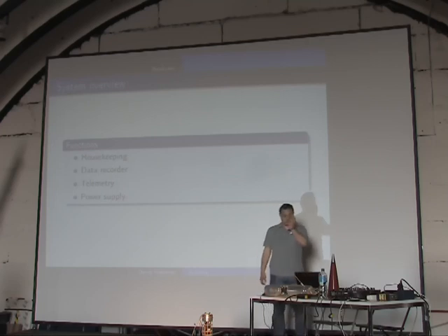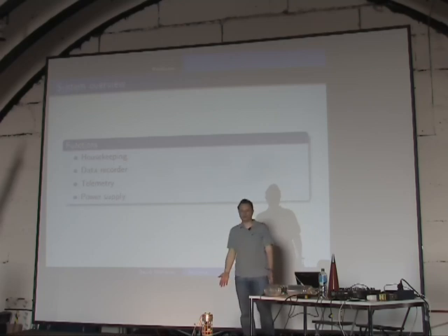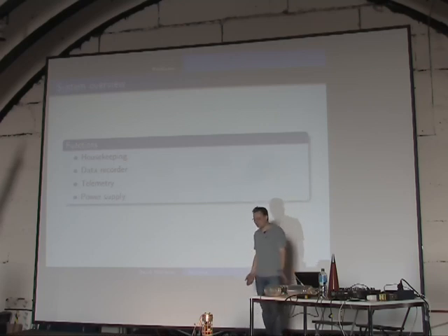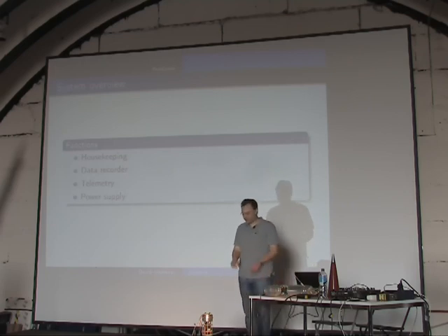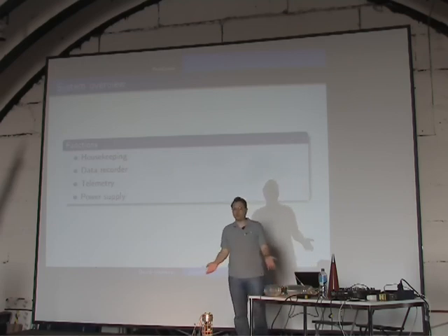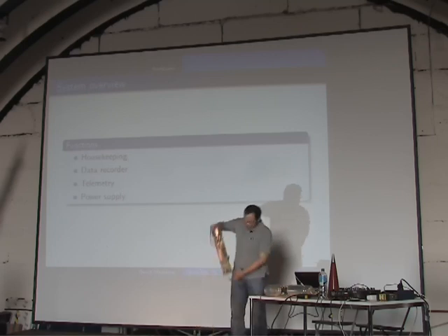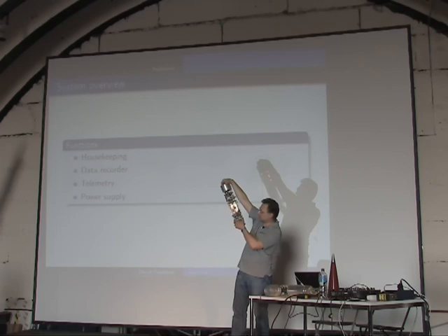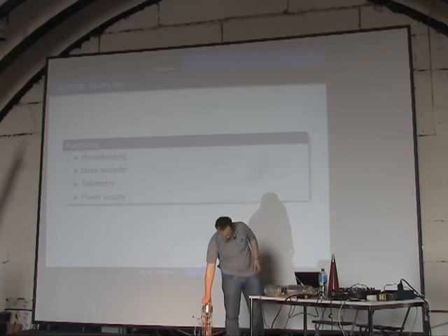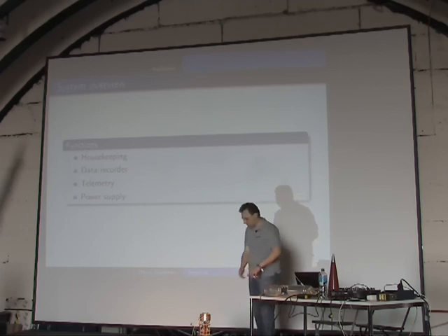We use them too, and especially at high acceleration and vibrations, something goes wrong. Or maybe it's just a little bit of humidity and you have corrosion, and then at the moment of liftoff, something just moves and then you have no contact and no power. Okay? So to avoid this, we designed a special compartment, it's like a revolver. So 6 batteries in one compartment, and it works fine. Well, we'll see when it flies. It has never flown till this date. So this is the power supply.